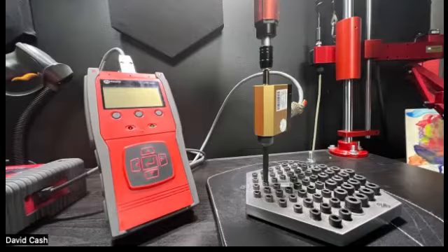Now, this value can and sometimes is different than when you test it on the analyzer with the joint simulator. But again, this gives you that ability to validate and verify that your tool is producing what you want on your part. And again, the analyzers have the ability to capture that data with a time date stamp and information regarding the tool for you to be able to collate and use in analysis down the road.